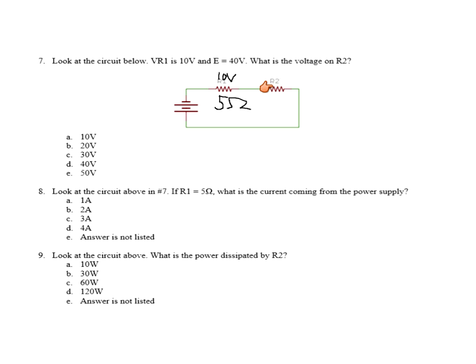Okay, well, what's 10 divided by 5 ohms? There must be 2 amps flowing in there. 2 amps in R1, 2 amps in R2, 2 amps total. I think I'm on the right track there. 10 volts divided by 5 ohms, yes. All right, so there's 2 amps flowing. I have 10 volts applied. What is the power going to be dissipated by R2?